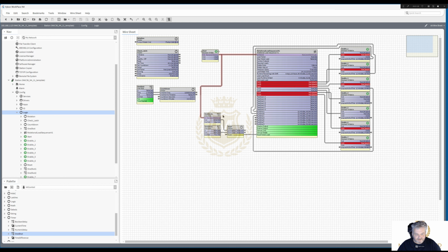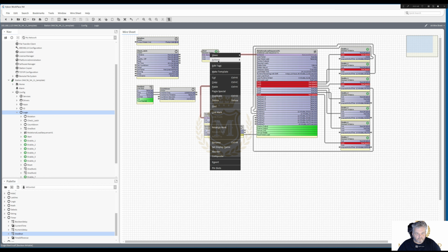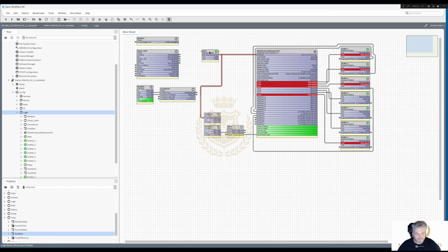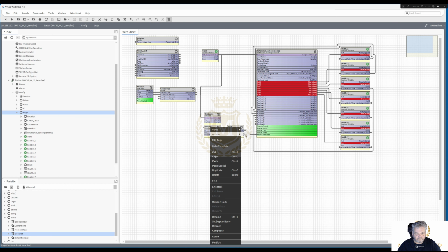That's clearing now because that is still on. So let's just take that out of its equation. We can actually cut it here. So turn all that active, so inactive and active, put all of them in alarm after 5 seconds. Now when we press the reset, it's only going to reset A to F and the G is not going to reset. Let's just prove that to you.